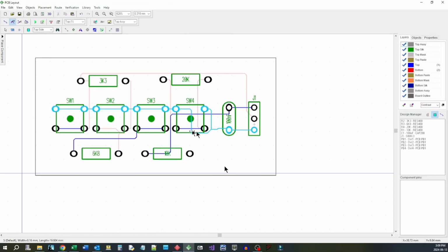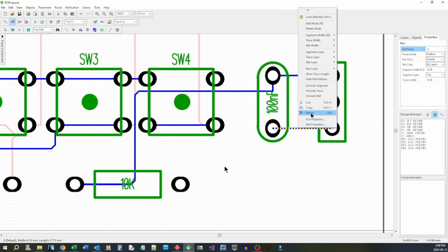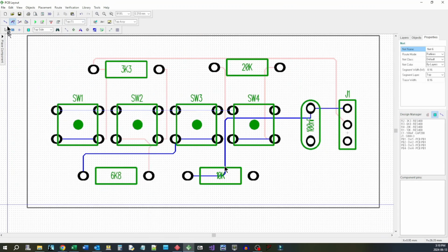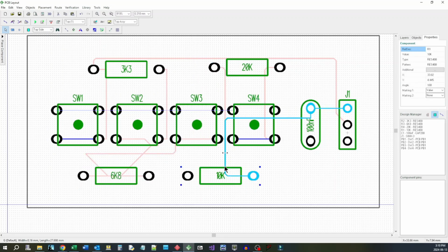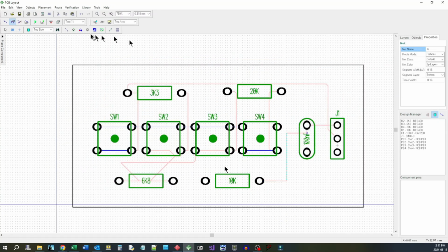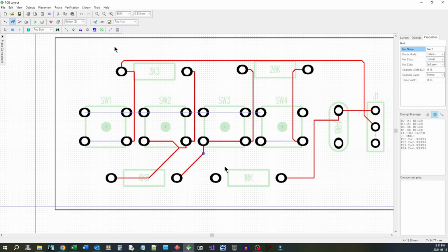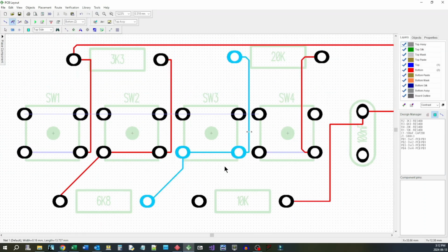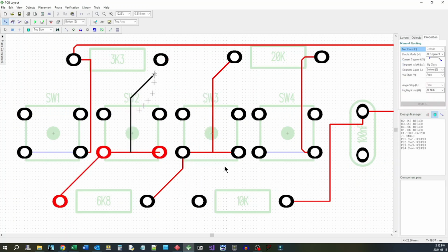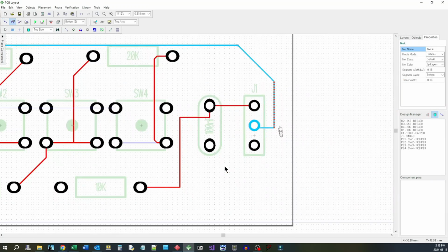So what I'll usually do is I'll take a first stab at the physical arrangement, and then I'll use the auto trace feature in DipTrace. And generally speaking, that's very unsatisfactory. So I'll go in and rationalize things. I'll move the components about, I'll move the traces about, so that it makes a more rational layout. And that's the process we're going through here.